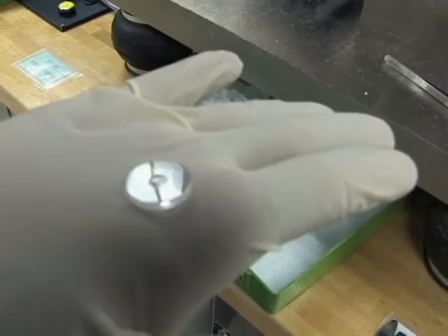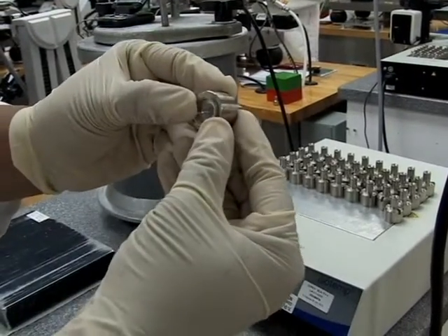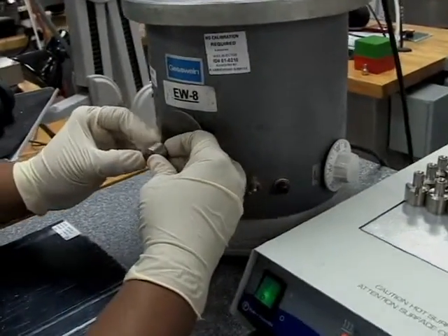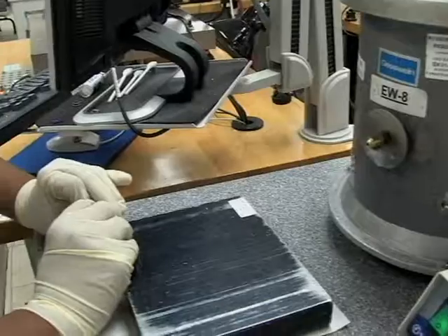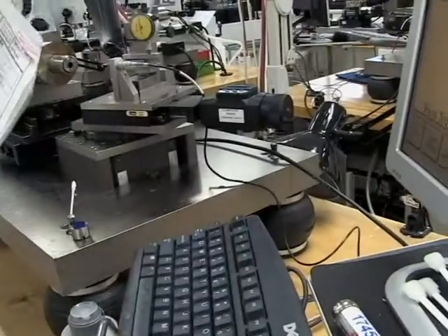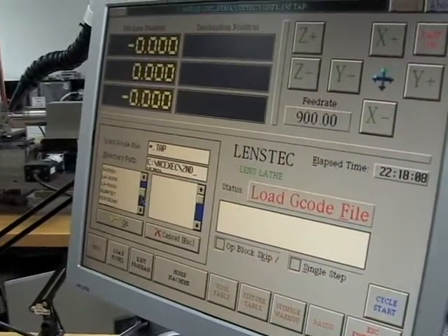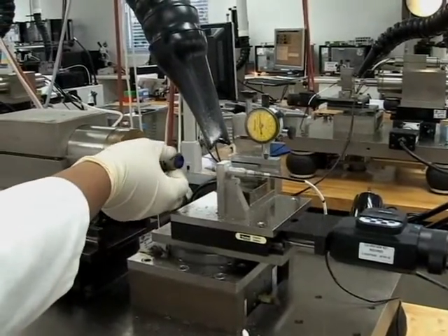After the concave side of the lens has been cut, the next step is the blocking process. This is where the concave side of the lens is placed onto a metal block that has been preheated to a specific temperature. We then move on to cutting the second side, the convex side of the lens. Convex is where at least one surface of the lens curves outwards like the exterior of a sphere.